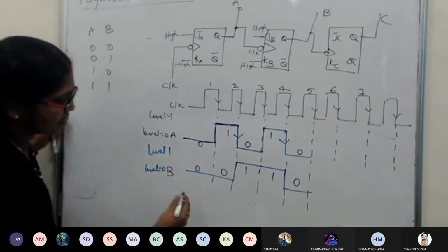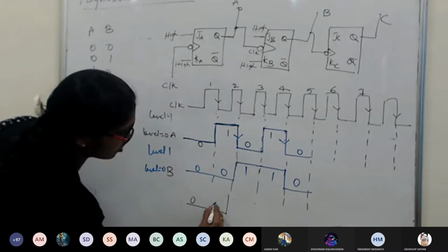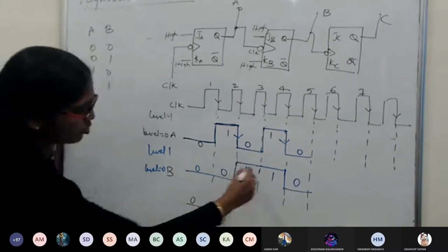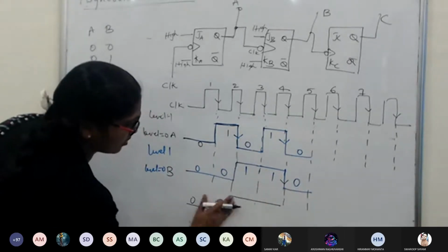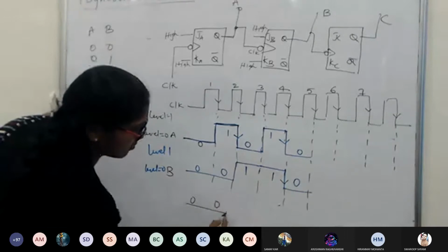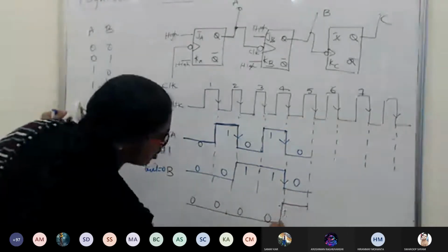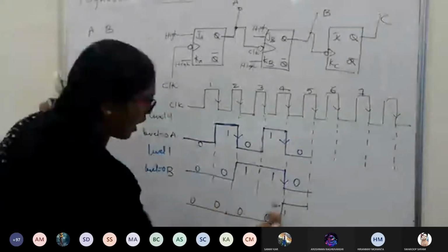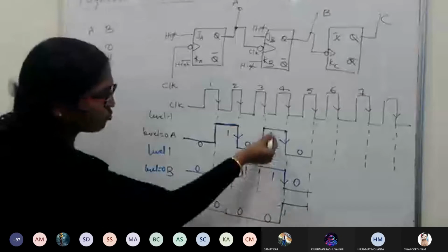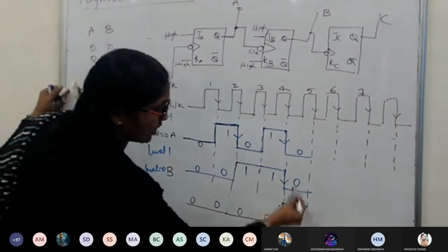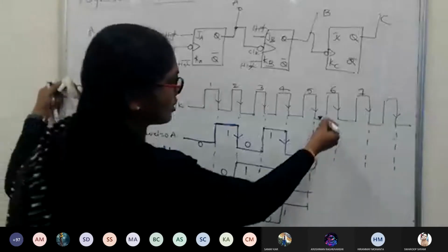Now C means what? I can start with this. It is following B, so over here till that level, this is 0, 0. Then I am going to the negative edge, so at this level it should change. At this level, it will change. Is that correct? So now you can see 0 0 0, 0 0 1, 0 1 0, 0 1 1, then 1 0 0. Then if you continue, you will get it or not? Just see.